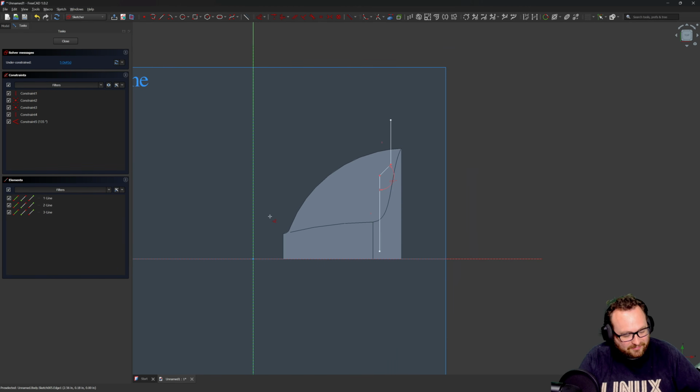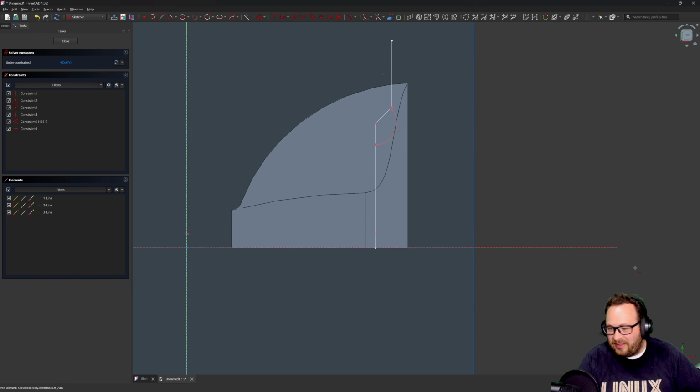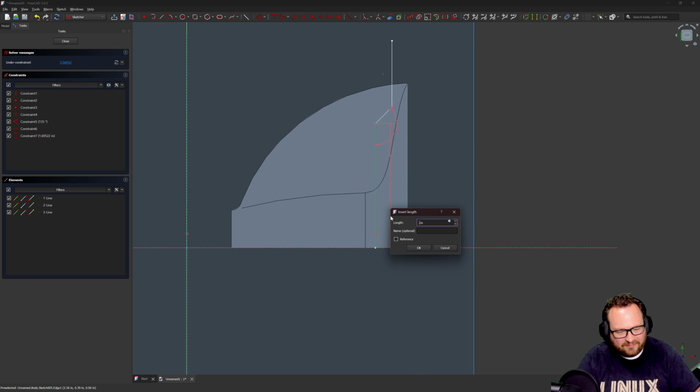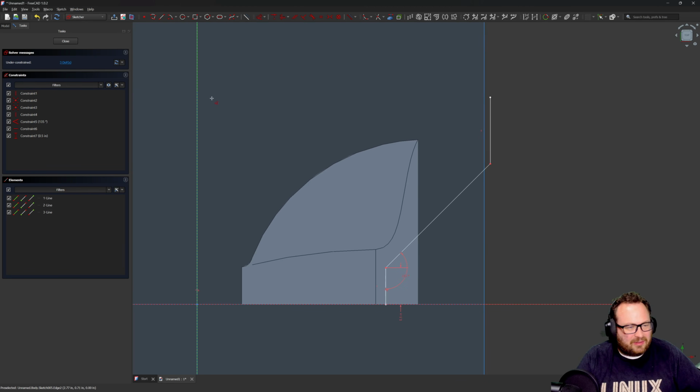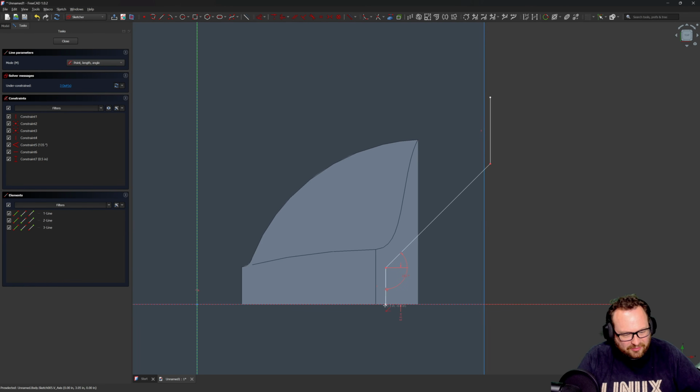truly correct angle. I'm going to hit H for horizontal. We'll select my origin, select this line end here, and then I'll probably do D for dimension and give this a distance of 0.5. Now I'm going to create like a little floor there and a vertical. Again, I could be using multi-line or polyline to make this even easier.